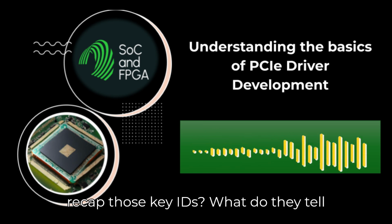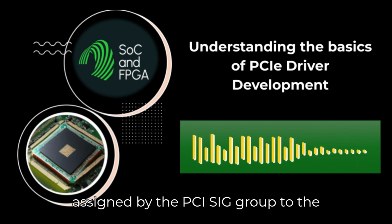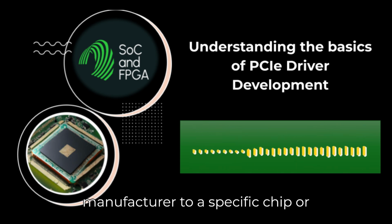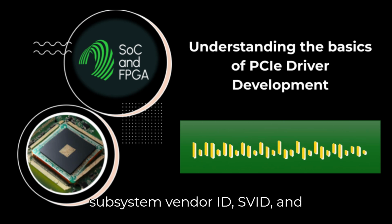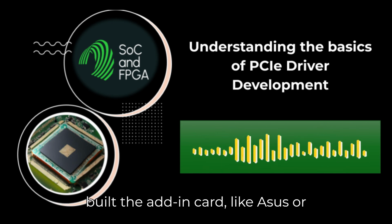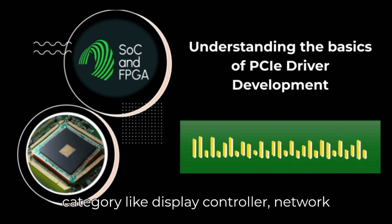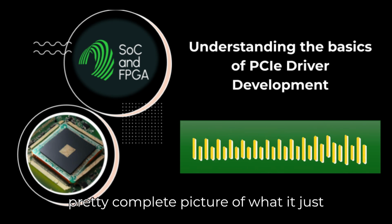Can you quickly recap those key IDs? What do they tell us? Sure. Vendor ID, VID. Assigned by the PCI SIG group to the manufacturer, like Intel or NVIDIA. Device ID, DID. Assigned by the manufacturer to a specific chip or product line. Then you often have subsystem vendor ID, SVID, and subsystem device ID, SSID. These identify the company that actually built the add-in card, like Asus or Gigabyte, and the specific model of that card. Finally, the class code, a broader category like display controller, network controller, mass storage controller, etc. Together, they give the OS a pretty complete picture of what it just found.